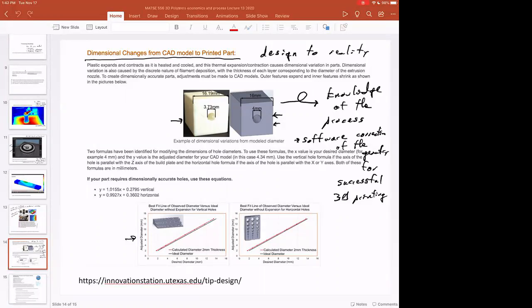So it's like material extrusion AM, or it is material extrusion AM, but it's a mostly metal filament with some polymer binder in there to get the thermoplastic behavior. But when you sinter that metal, because there's a bunch of plastic in there, the part shrinks. And so they have embedded in their design software and in their print planning software that shrinkage.